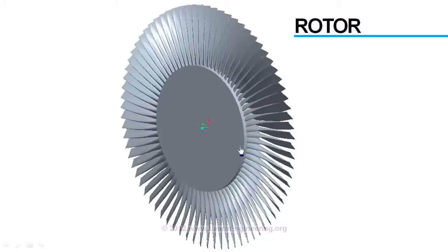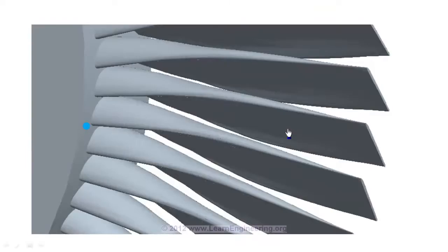If you take a close look at one such blade, you can observe one thing. This blade is a collection of different airfoil cross-sections set together, which vary in size and shape from bottom to top. When high-energy steam at inlet, the steam with high pressure and temperature, flows over such a blade, it will induce a pressure above and below the blade. And thanks to the special shape of the blade, the pressure above will always be less than the pressure below. So, there will be a resultant net force acting in the upward direction. This force will make the blade rotate, in this manner.